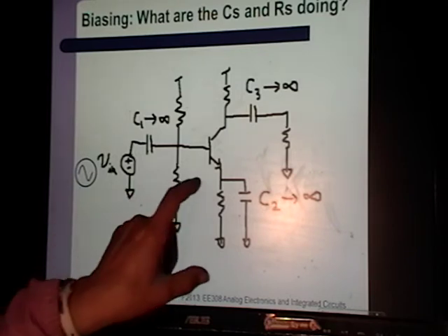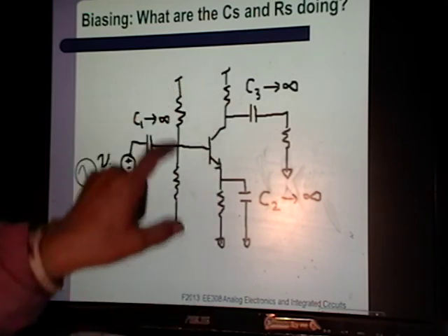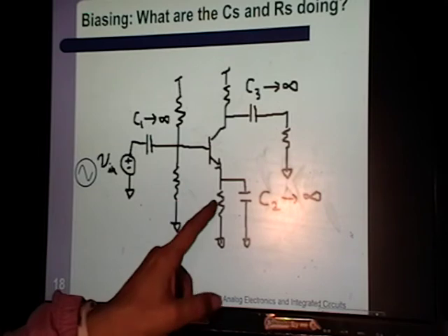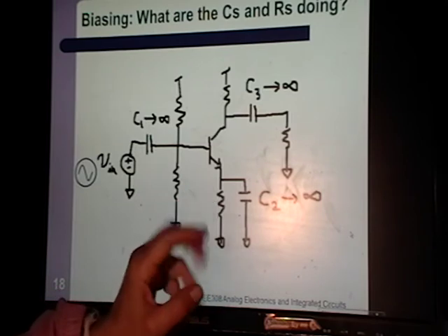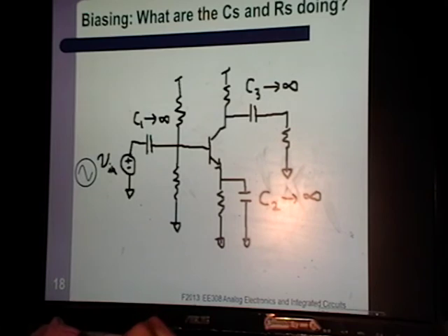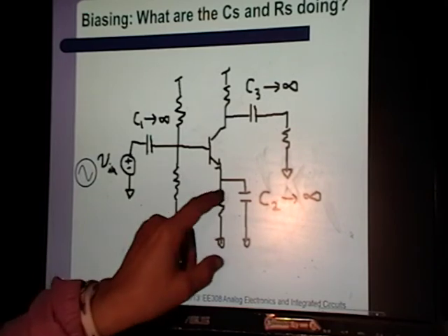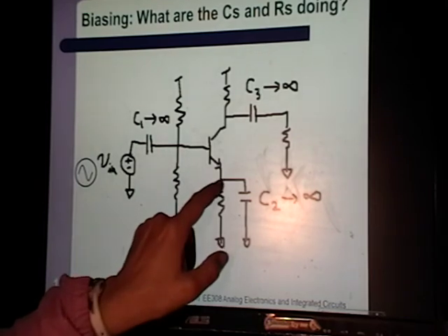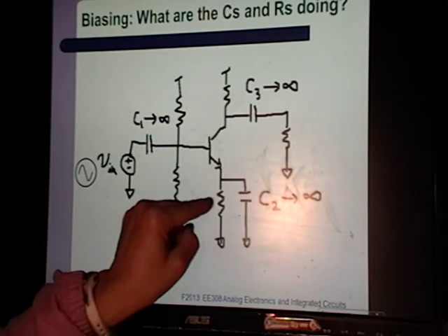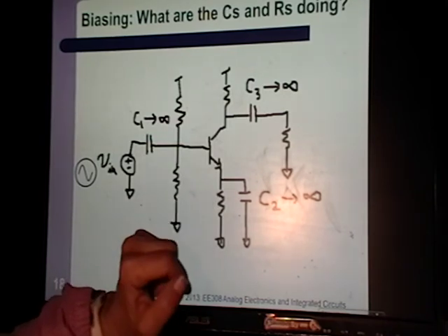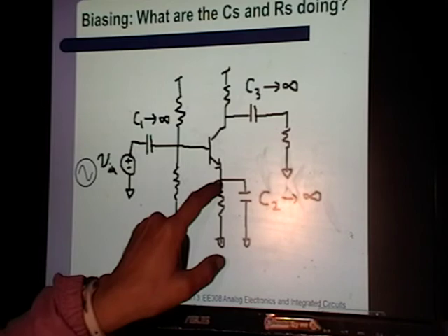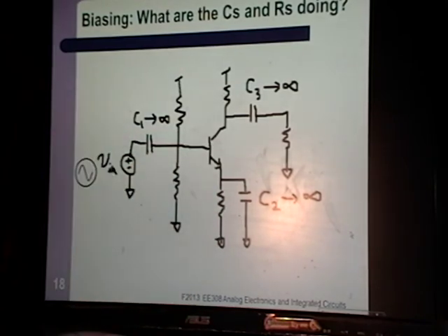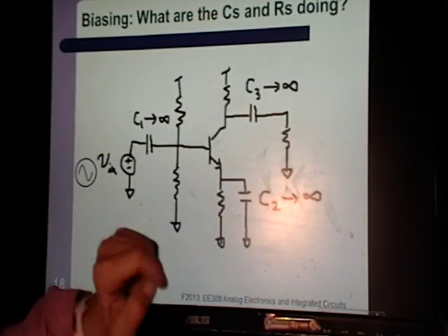When you built the 4 resistor biasing right here, you had this resistor down below the emitter. You probably looked at it and said, oh, that's a degeneration resistor. It's actually not. It's setting the voltage at the emitter. If you remember how you calculated that, you calculated that for a DC value. So this is a biasing resistor. It's not degeneration. If it's trying to set the voltage at this node, when you're operating your amplifier, you don't want this node to move. If that's a bias voltage, you want it to stay constant.